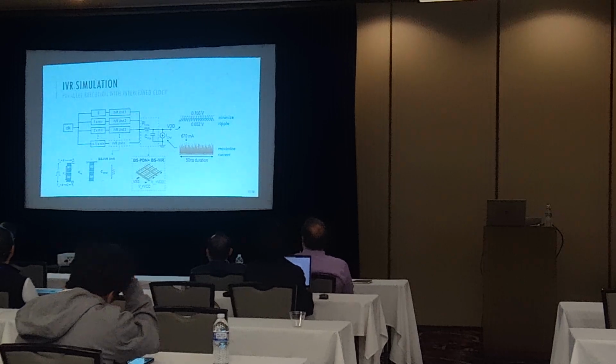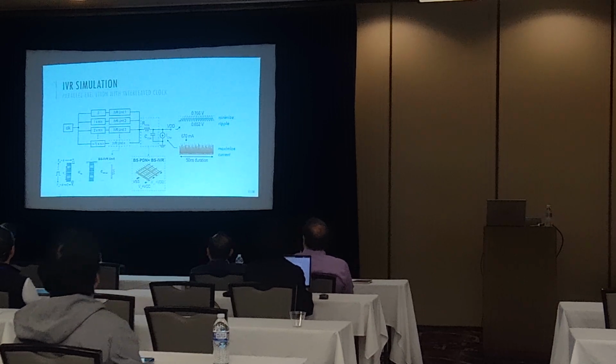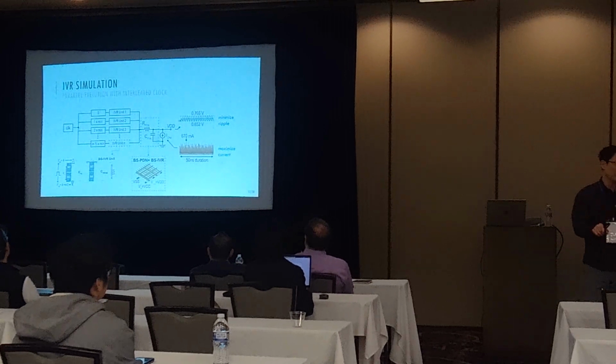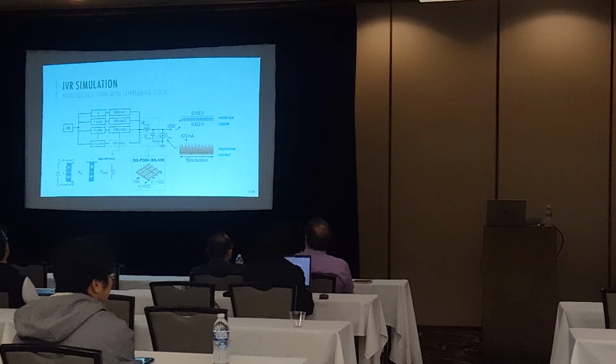All right, so once you're done with the schematic design, sizing, and layout, we're going to integrate it into the full chip, and we're going to do simulation. Again, like I said, we're not going to use just one gigantic IVR. We're going to split it into multiple and have them collaborate. We're going to use interleaved clock signals to make some of these work at the same time, in parallel execution. Individually, they're smaller than one monolithic IVR, but they can work together to manage the voltage level. So now, an experiment using parallel IVRs.